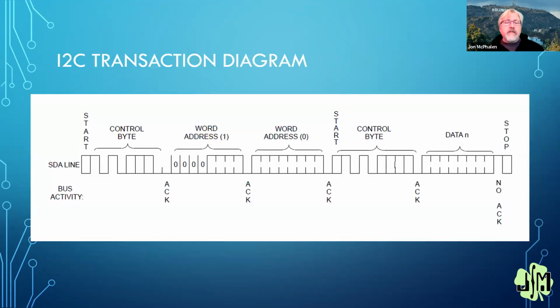When you get into I2C, you'll often see transaction diagrams like this in documentation. This is from an EEPROM thing. So the beginning, this section is called the control byte, or you'll sometimes see it called slave ID, because this is the device we want to talk to. And then this section here, the addressing will be device dependent. In this case, this particular EEPROM requires 12 bits. The EEPROM on the P1 has 2 address bytes like this as well.